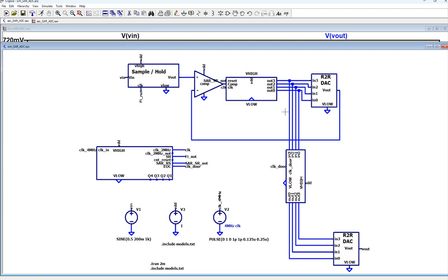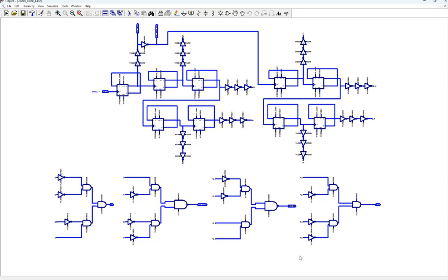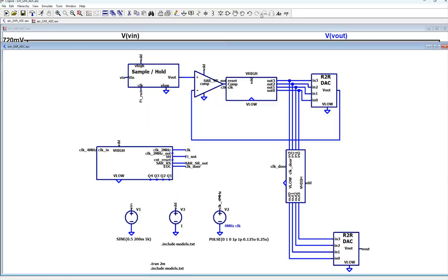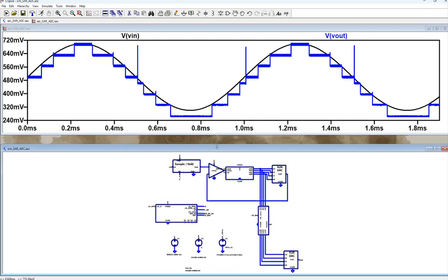And after this is ready, you should directly put a rising edge and send it out. And that is why you are seeing that plot, right? I paused it, but you can see that's how you are seeing this plot. And if you do the math, it's actually very reasonable because 4 bits, right? 4 bits is giving you how many stages? No, I'm not saying the SAR stages, but I'm saying the resolution stages. 16, right? 2 to the 4th, right?